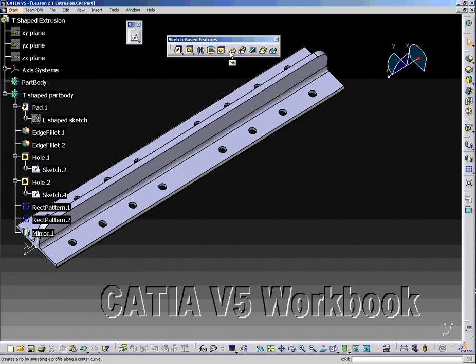The Rib tool creates a rib by sweeping a profile along a center curve. This creates the profile sketch, then creates another sketch defining the curve or path. The Rib tool creates a rib by sweeping a profile along a center curve. It creates a profile sketch and then creates another sketch defining the curve path that the profile will be swept